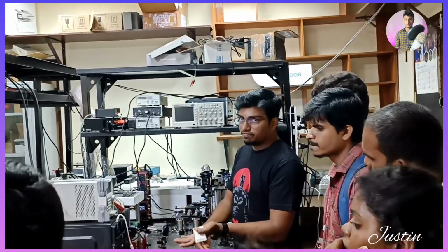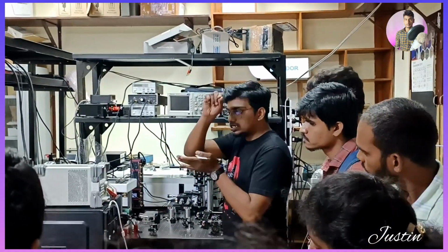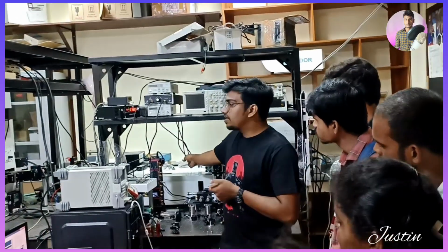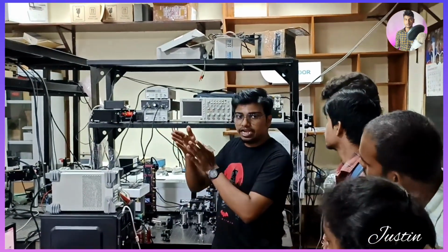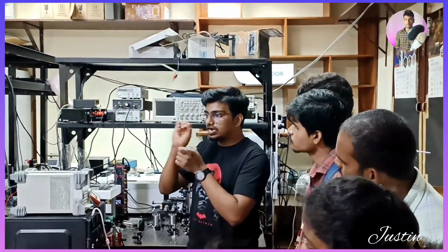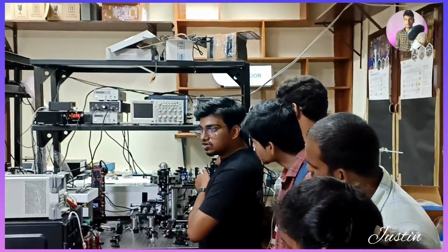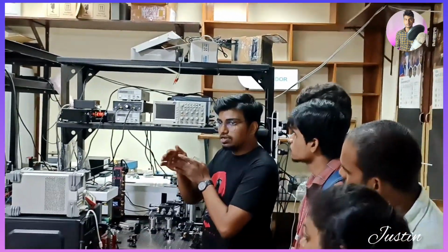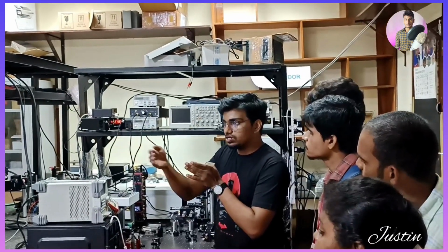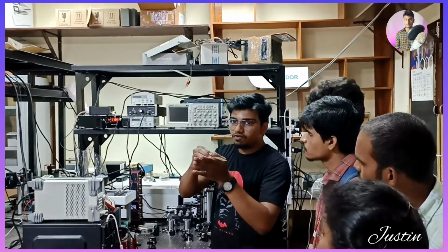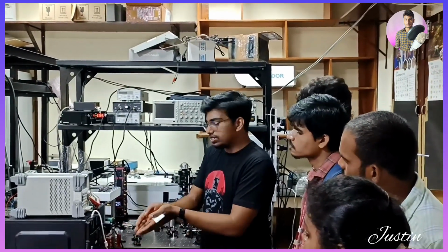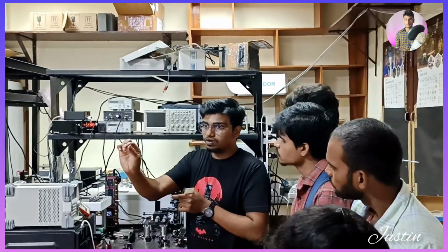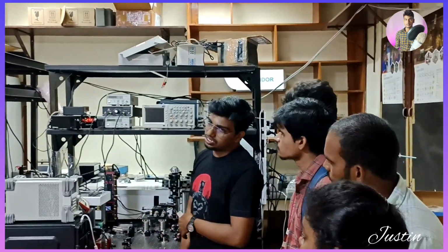And if you want to measure the fluorescence lifetime, how fast it is decaying, we can couple this into a lifetime measurement unit. We have an avalanche photodiode. That is a photodiode which is highly reverse biased. These are normal silicon photodiodes, which have some cutoff, which means they won't work at very low intensity, they need lots of photons to work. Like the photoelectric effect, you are putting in some photons and you get voltage. So there is something called an avalanche photodiode. It is highly reverse biased, which means if you have only a single photon, it will give you some voltage.